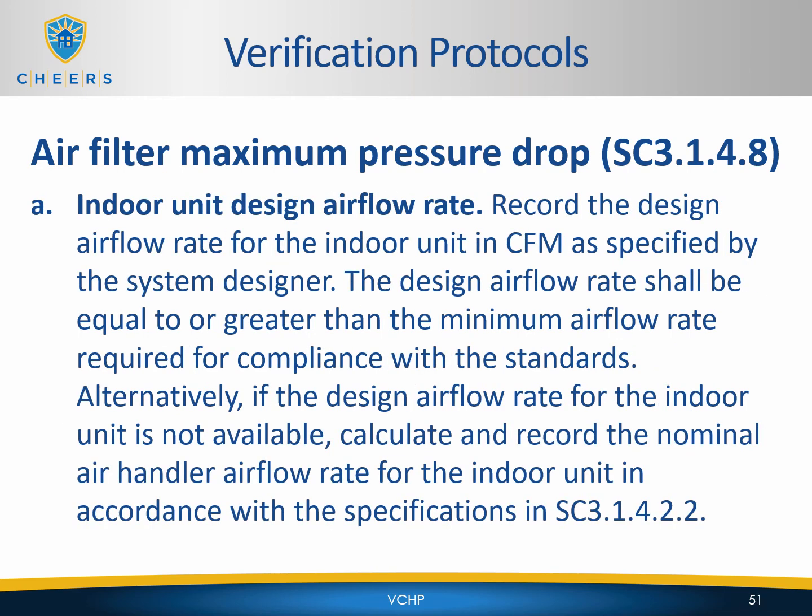Indoor unit design airflow rate. Record the design airflow rate for the indoor unit in CFM as specified by the system designer. The design airflow rate shall be equal to or greater than the minimum airflow rate required for compliance with the standards. Alternatively, if the design airflow rate for the indoor unit is not available, calculate and record the nominal air handler airflow rate for the indoor unit in accordance with the specifications in SC 3.1.4.2.2.